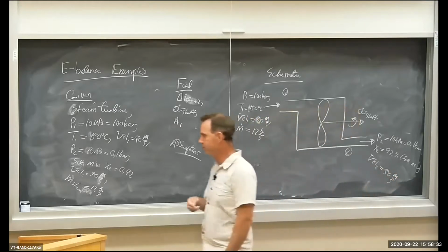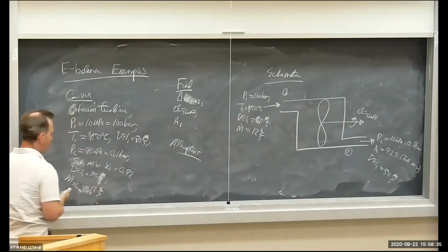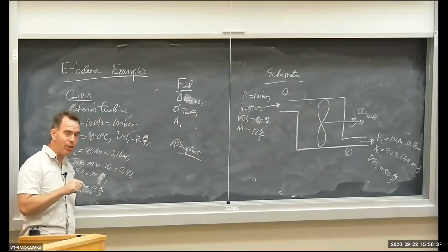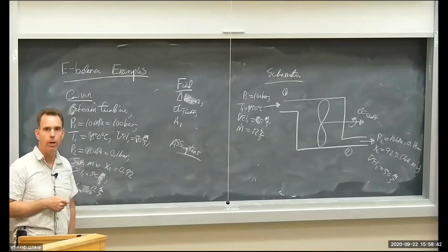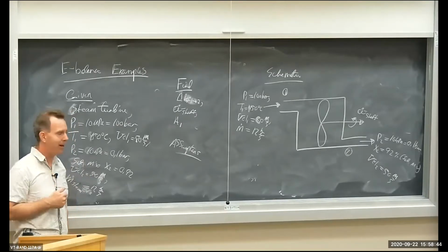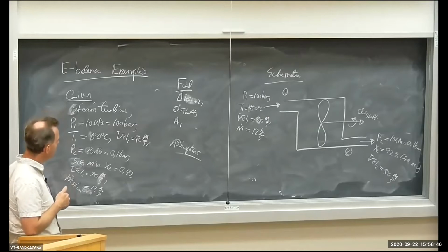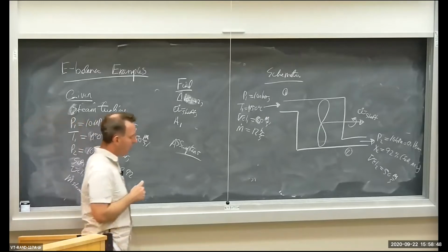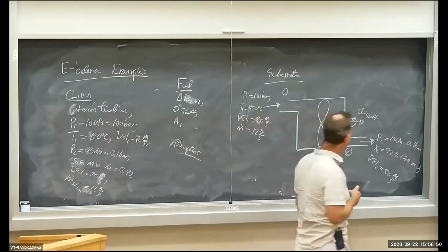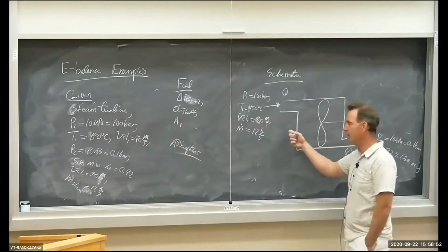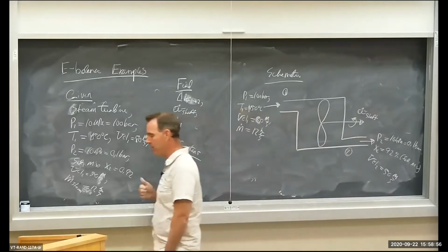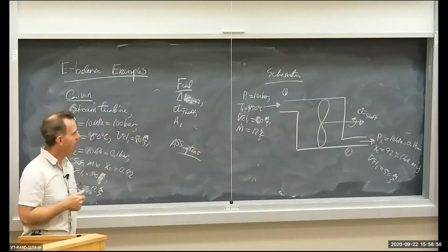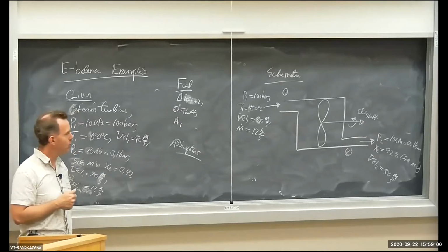Okay? Pressure, velocity, and we'll find out enthalpy have fallen because we're extracting energy from the flow to produce shaft power or shaft work. What are we supposed to find? We're going to find the change in specific kinetic energy from the inlet to the outlet, so delta KE. We want to find the shaft power, W dot shaft, produced by the turbine.